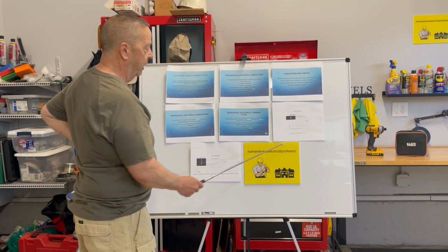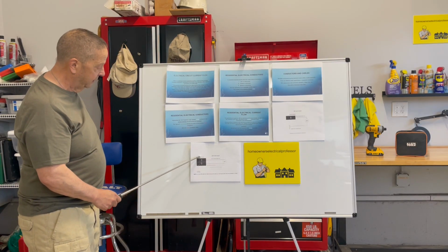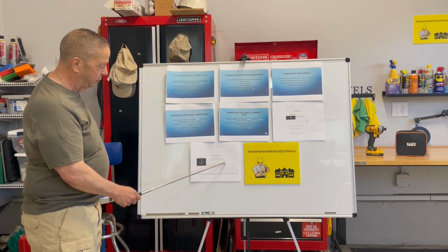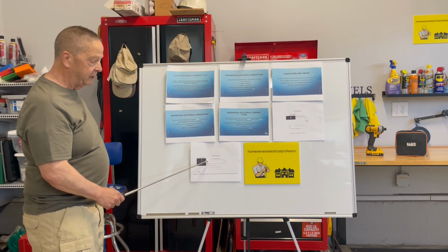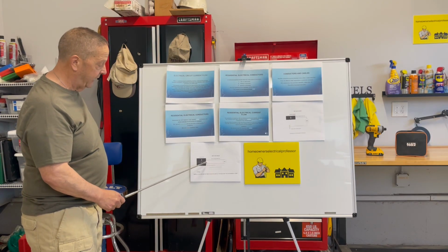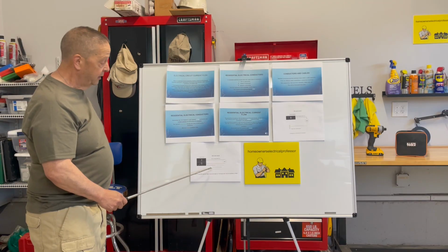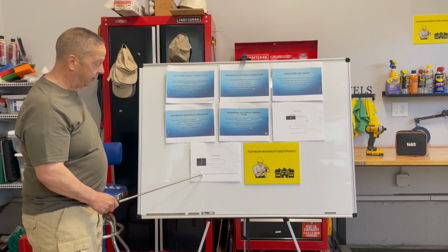A 240 volt circuit, a 2-pole circuit breaker, the black wire, the load goes out. On the red wire, it comes back. Now, in a piece of two-conductor cable, which we'll go over later on, a black and a white, you can, under the National Electrical Code, take the white wire and identify it as black with tape at both ends.